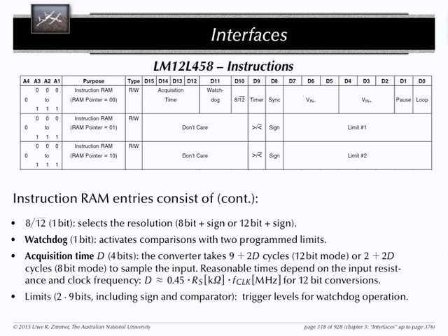You can set your AD converter into watchdog mode. What does that do? Isn't it if you don't get the output by a certain time, you reset? Or you enable an interrupt. It's not fast enough, I think. What is not fast enough? Like the output time, so you take too long to convert that bit. Good idea, but no, that's not what that means. In this case, it looks like you're actually checking the values between two limits. Yes. So your concept was watchdog in time.